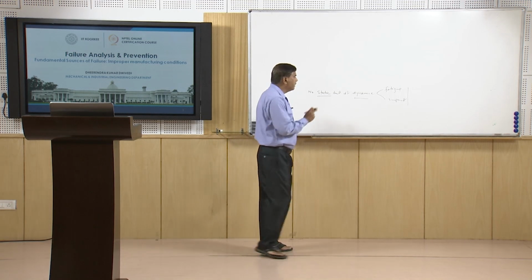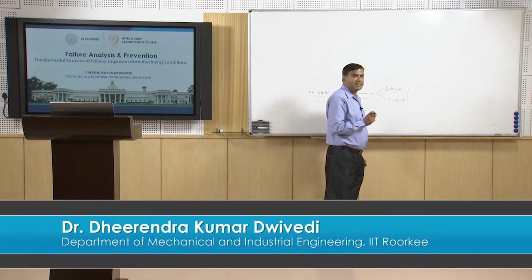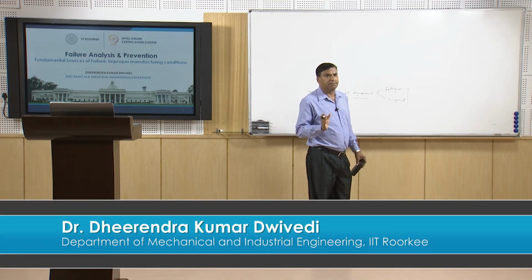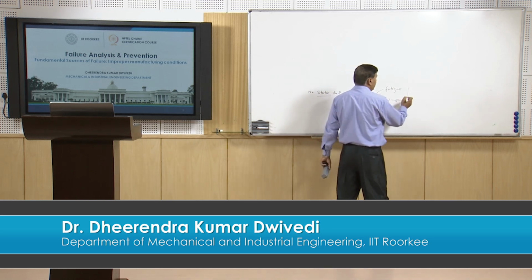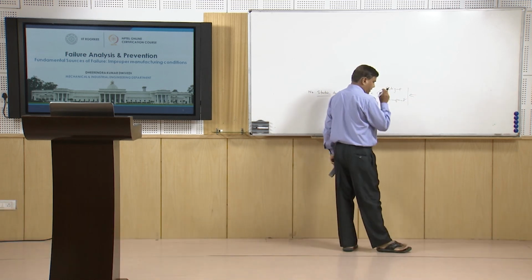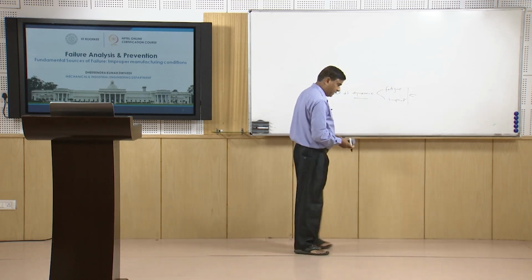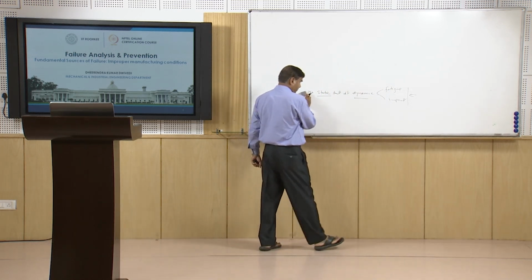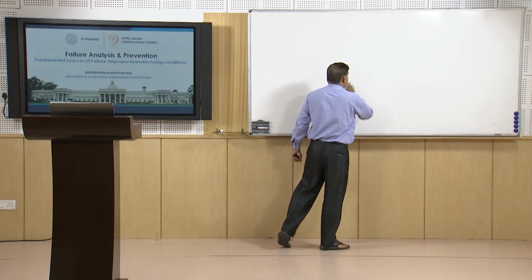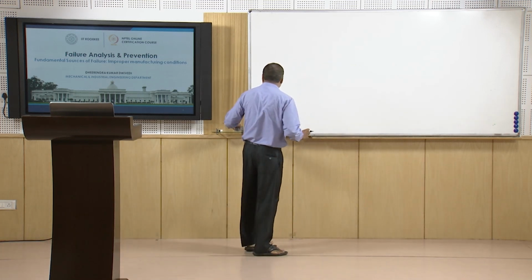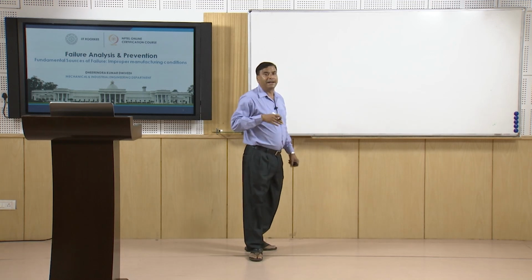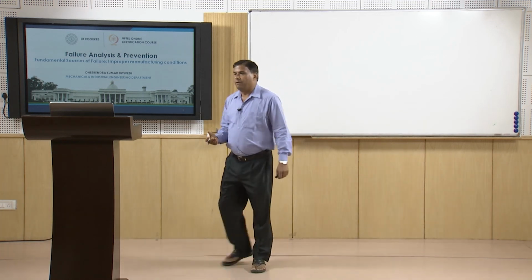Therefore, if such stress raisers are present in the form of an indentation mark, then under fatigue and impact conditions, such marks will facilitate the nucleation and growth of cracks easily, and therefore the presence of indentation marks, especially in high stress areas, becomes more harmful.